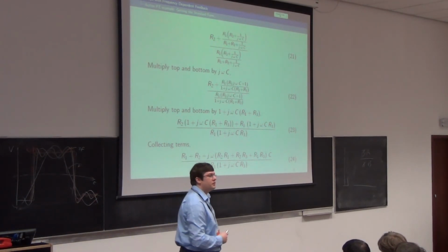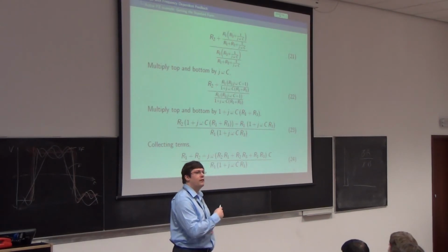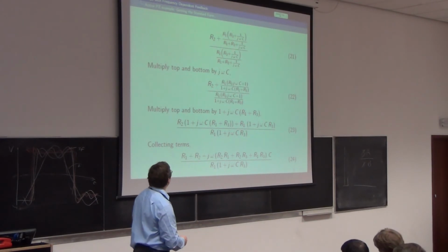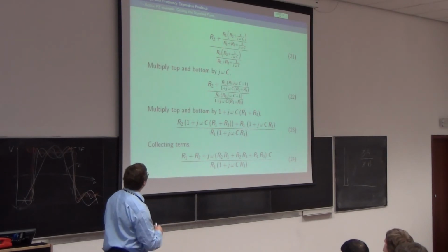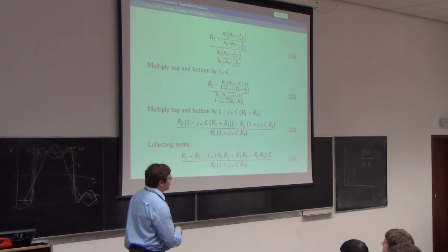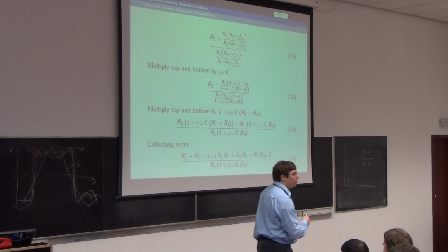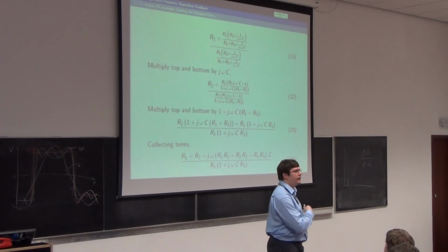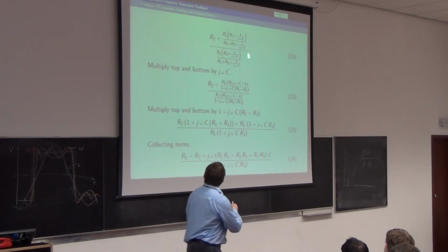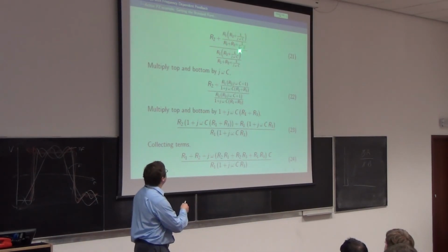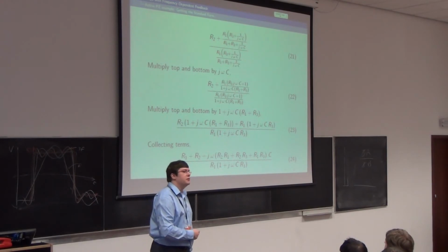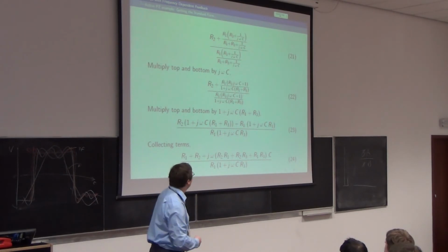If I multiply through to undo the parallel signs, which are not real mathematics, I will end up with this. And I've got to get back towards an S tau plus 1 on the bottom and an S tau plus 1 on the top and a K out the front. So I've got my R1 plus R3 plus 1 over j omega C. I did this one in j omega just in case you don't like tau.